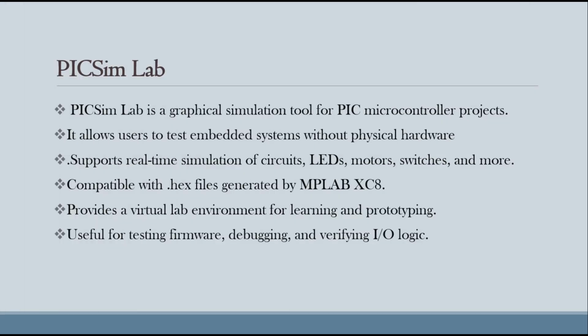The third one is PicsimLab. PicsimLab is a graphical simulation tool for PIC microcontroller projects. It allows users to test embedded systems without physical hardware. It supports real-time simulation of circuits, LEDs, motors, switches, and more. It is compatible with .hex files generated by MPLAB XC8. It provides a virtual lab environment for learning and prototyping. It is also useful for testing embedded firmware, debugging, and verifying input-output logic.